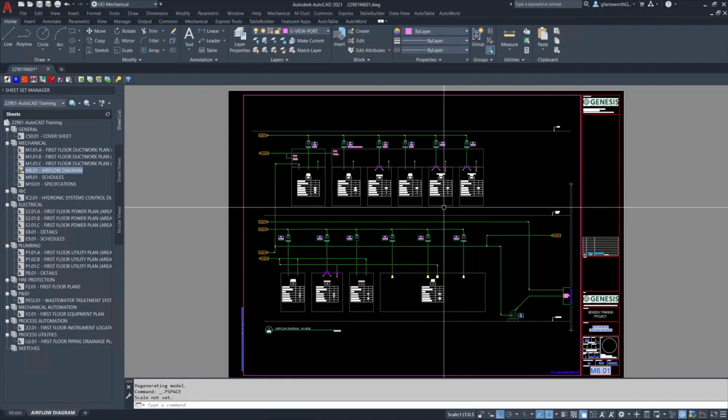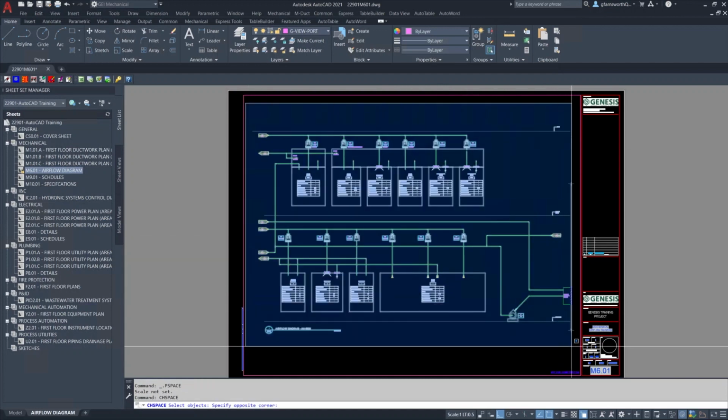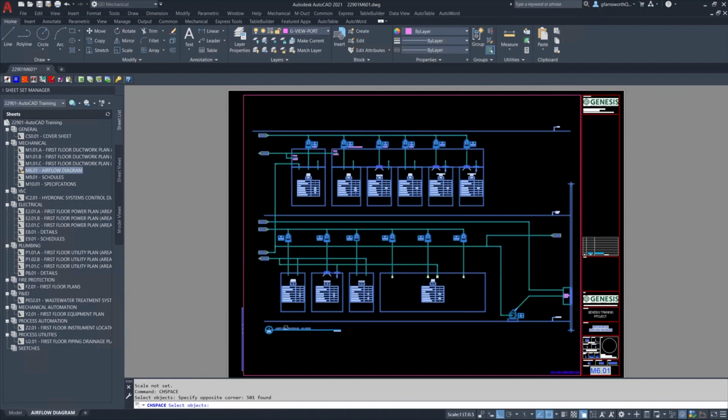Now that we have a viewport and reference rectangle oriented to the origin point, we can simply use the Change Space command to move our paper space items to model space. The command is chspace, also found in the Modify menu, Change Space. Next, select the elements you want to move to model space. Be sure to only select the drawing elements. There's no need to select the view title because Revit will create one when you insert the view on a sheet.